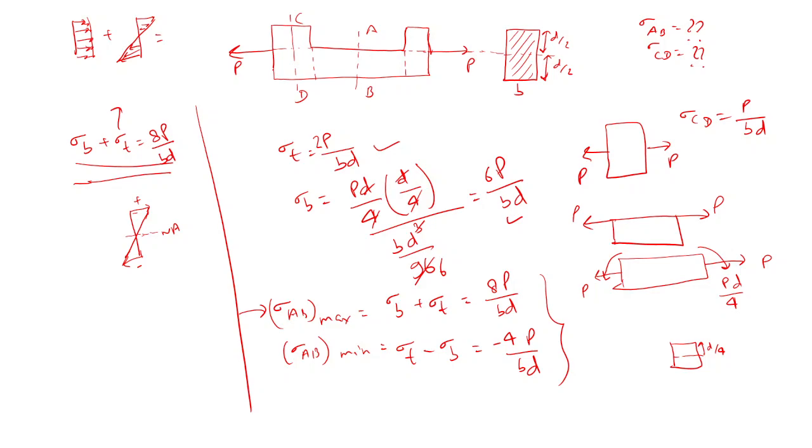Here additionally, if we had shear stress, we cannot add directly. Generally, I'm asking if we had additional load such that we have shear stress, we cannot directly add those. No, that time we can't. If shear stress also comes, then Mohr's circle etc. will come into the picture.